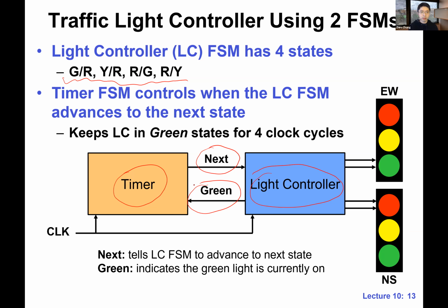Since we are counting, we can quickly wrap around. We only need 00, 01, 10, 11, and then we wrap around and go back to 00. We only need 4 states. Make sense? We are going to talk a little more about the difference between Mealy and Moore, and the trade-offs and implications.